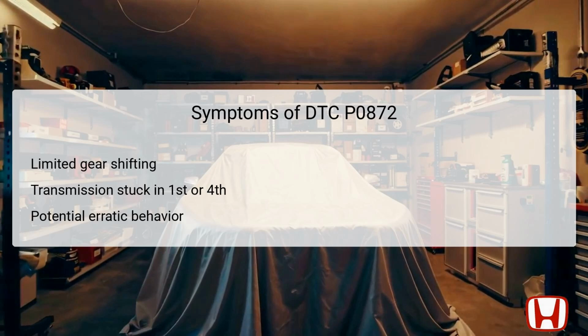pressure switch. Furthermore, drivers may observe or experience erratic behavior during operation, characterized by abrupt changes or lack of responsiveness when attempting to shift gears. Such symptoms are critical to recognize, as they can lead to further mechanical issues if left unaddressed. Drivers may also perceive unusual engine performance or increased RPMs while operating in lower gears, which further indicates a problem with the transmission system. Timely diagnosis and repair are crucial to ensuring vehicle safety and reliability.